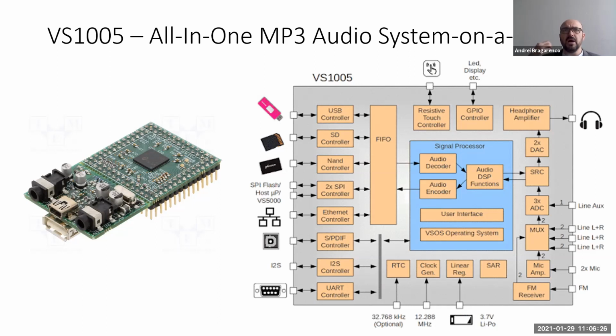But the video display controller, the keyboard controller, the USB controller, the audio controller, and everything else is put inside the Broadcom chip. That means when we are speaking about the Raspberry Pi, we don't have a powerful processor there. We have a very complex system on chip, an all-in-one pocket PC. In this case, I will give an example of a chip that we can use to have a player.